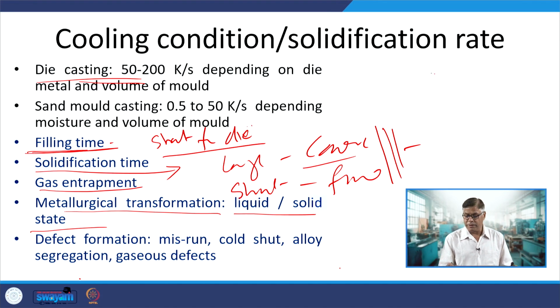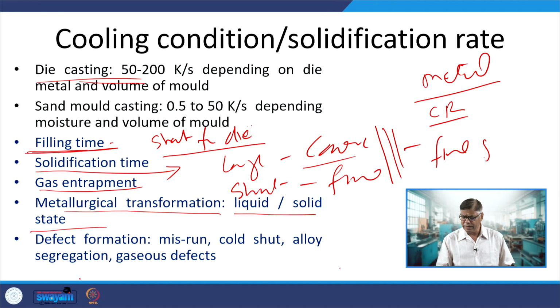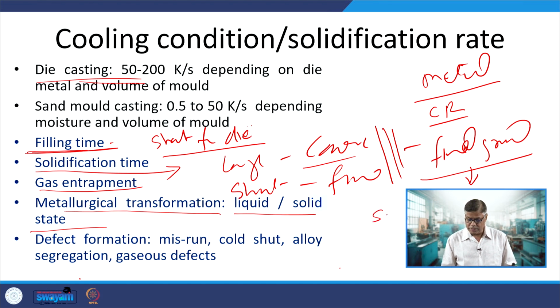So, this is very important, especially as it will depend upon the kind of metal system. For metals where there is no solid state transformation in terms of the phases, whatever cooling conditions are imposed during solidification in the liquid state will define the final grain structure. Whatever grain structure is developed during solidification will be final. So, if a slow cooling rate is imposed, then a very coarse grain structure is achieved, and if the cooling rate is high, then certainly we will get a fine grain structure.